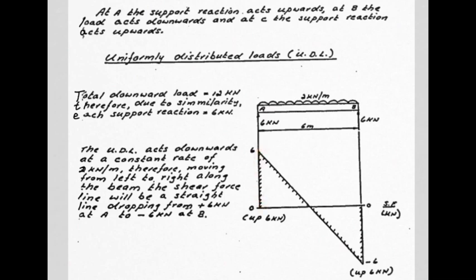And then as we slowly slide our hand to the right and expose more and more of the left-hand side of the beam, we would have a cumulative effect of lots of tiny little loads as we move along, which is essentially what the distributed load is. And that would knock our line down, down, down, further down, exactly as the point loads did in the last example. But this is progressively, smoothly applying those consistently all the way along.